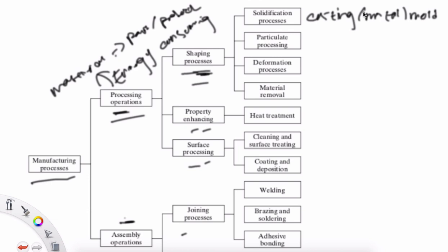And here in the solidification process, the starting material is heated liquid or semi-fluid, and it can be poured or otherwise forced to flow into a mold cavity while it cools and solidifies, taking a solid shape that is the same as the cavity. So it will make a geometrical product as we need.